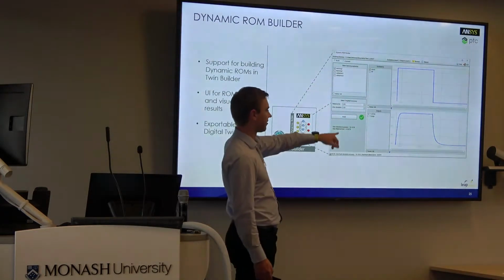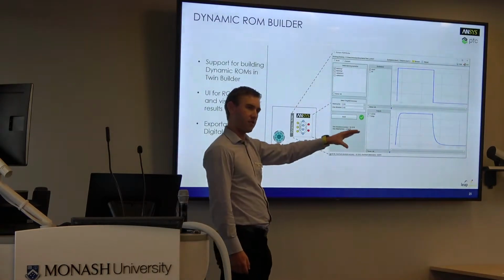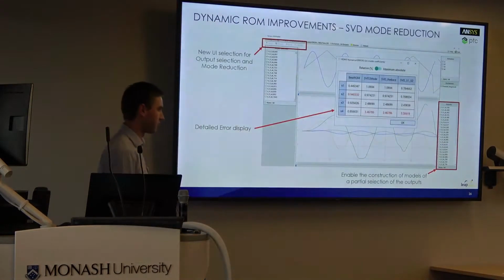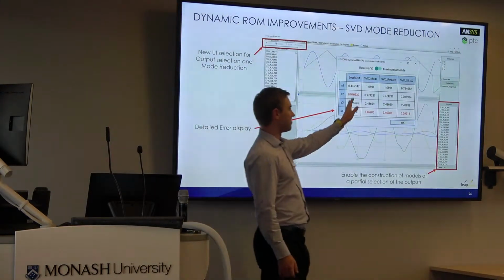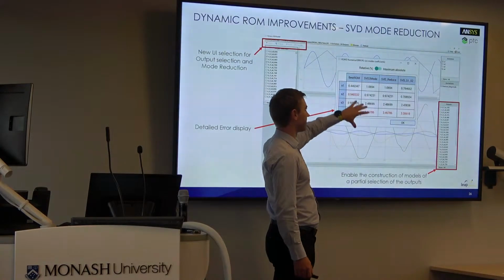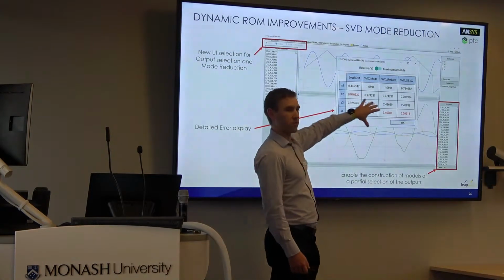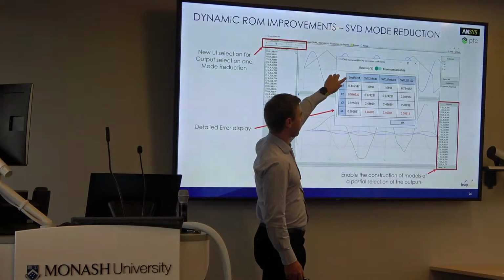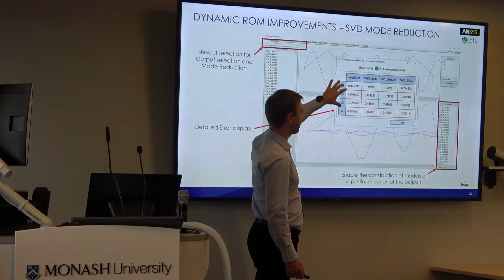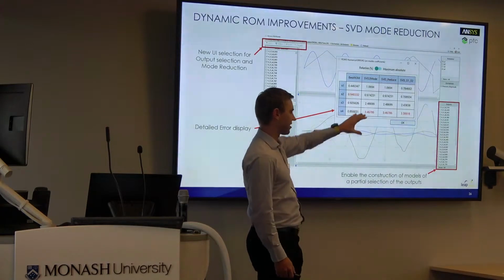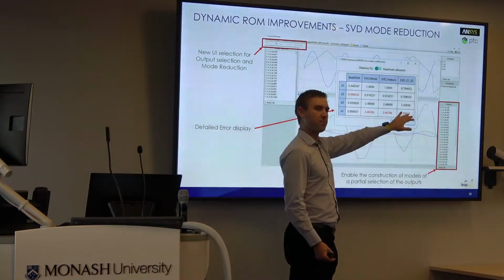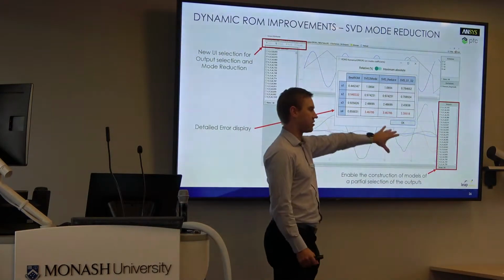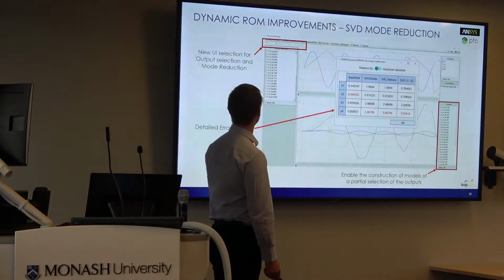So once you've loaded these, it's just a matter of clicking build, and you can watch it as it converges to a final answer. There are a few enhancements to the tools we have to do it. We have a nice new tab interface, which makes this a lot nicer to use. You can save multiple versions of your same ROM and compare them to find out which ones struggle with which scenarios. So for example, they left the accuracy cranked up on the first ROM, and it doesn't really struggle anywhere. But they've started peeling off layers of the ROM in these other versions, and they all struggle with scenario 4. So it might be a case of you come back and you change which bits you stripped out of the background.